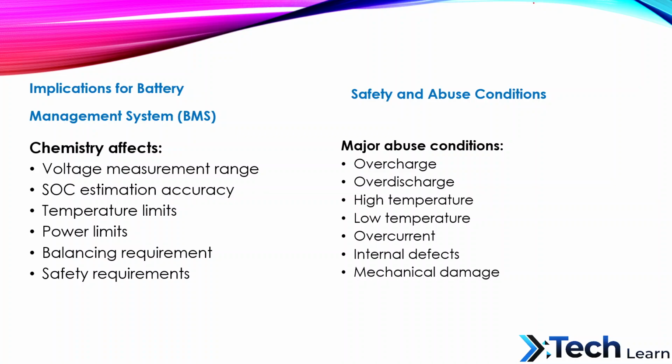Then coming to safety and abuse conditions, lithium-ion batteries must operate within strict limits. Overcharge can lead to thermal runaway. Overdischarge can cause internal damage. High temperature accelerates degradation and can trigger exothermic reactions. Low temperature charging can cause lithium plating. The BMS is primarily responsible for preventing all these conditions.